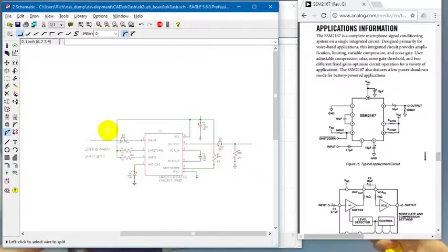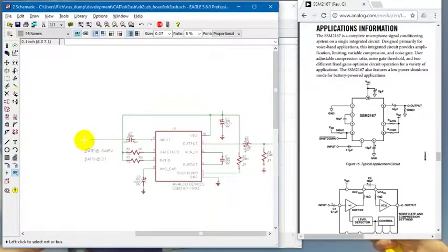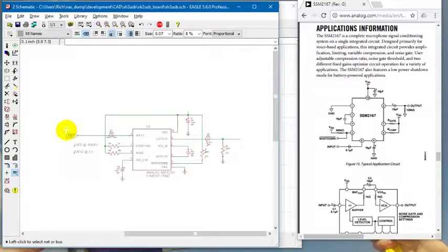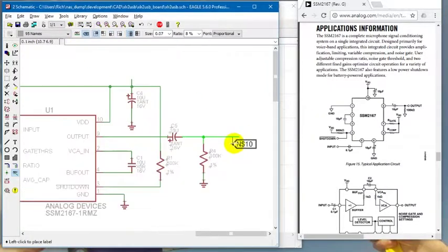So okay, the last thing that we're going to do is make some labels, and labels are cool, because they give a name to a net that's there, and it automatically changes. So I'll show you what I mean. First I went to that, and then I clicked a net, and it automatically populated it with the name $N$11. And there's a couple of shapes you can put around there. I like the shape that goes around this guy, and this guy right here, and you notice it remembered that I wanted the shape, and I just used my flip command to flip it around.